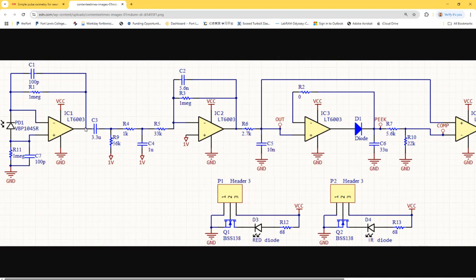Okay, so basically your signal information is oscillating around the arbitrary DC offset, which is bad. We just remove it. So this high pass filter will remove it, and then you add a known offset, 1 volt. So all the AC signal will swing around 1 volt. It's good. I don't know what the VCC is here. It's probably single supply.